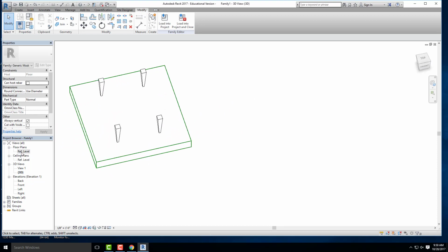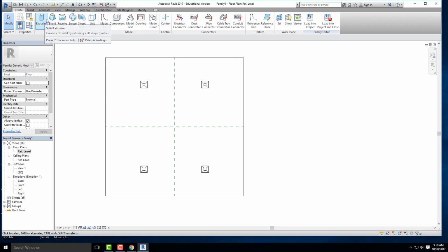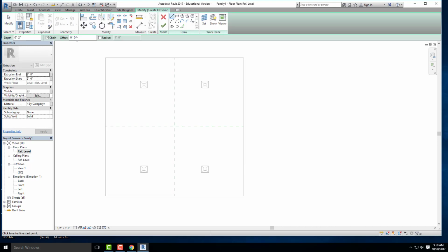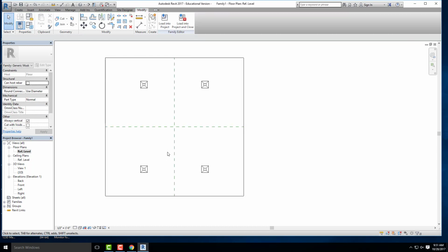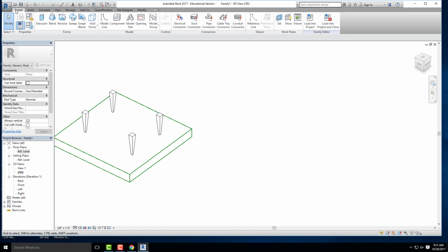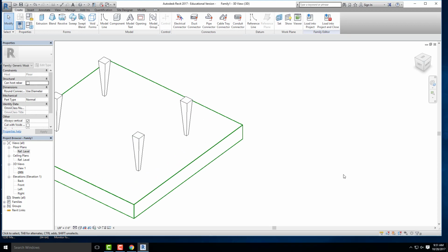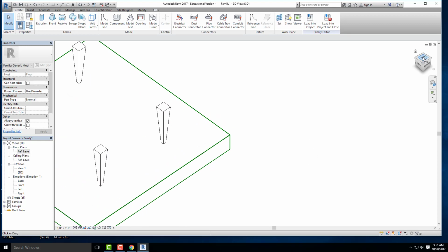Okay, so I'm going to go ahead and build a tabletop again before we move on to our next tool. Let's build an extrusion, just a basic one. I'm going to make sure that this tabletop is just overhanging. Create a new Workplane, just with the tabletop on. Yep. So I could use the reference plane. I could just say that it's 2'6" to 2'8" like we just talked about. But yes, we could change the work plane. So we could go over to create and we can go to set, pick a plane, and I could pick the top of those legs. Sure, that's definitely something that we could do.